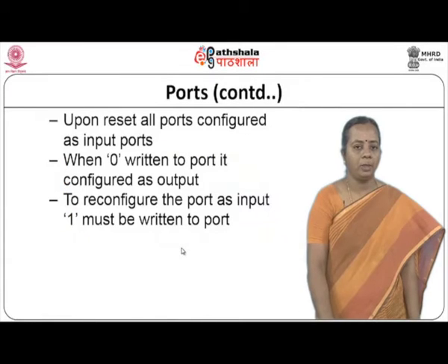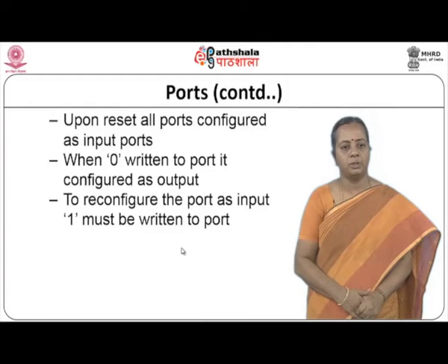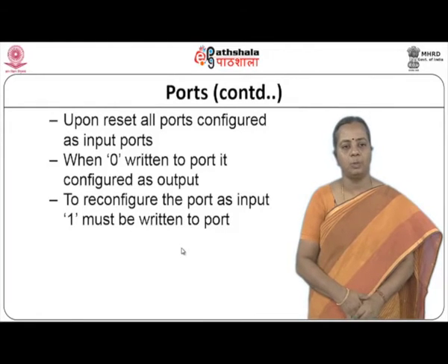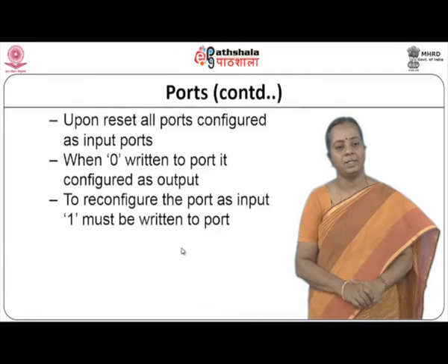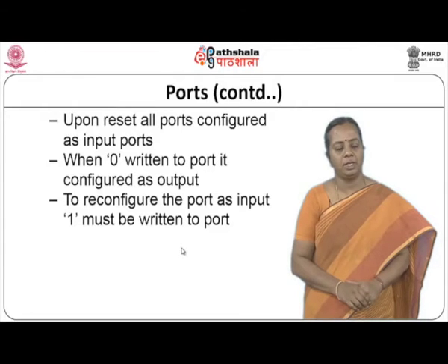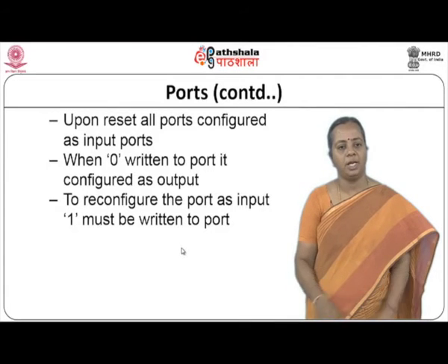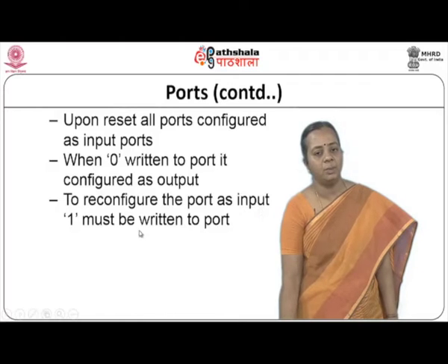When you are looking at the ports, usually all ports are configured as input ports. When I reset, or start at first, it acts as an input port only. If I write a 0 to a particular port, then it is an output port. If I write a 1 to the port, then it is an input port.